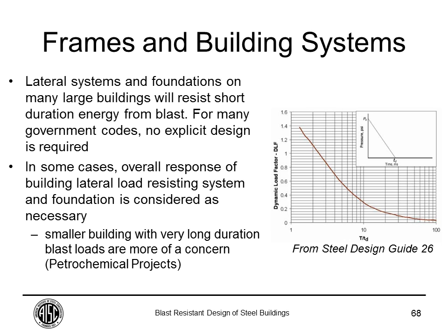So let's just talk about frames, which is the very last point in the outline. Generally, frames are not required to be designed for blast resistance because they have an inherent resistance to blast load. The main reason for that is, if you look at this plot on the right, the natural period of frames in terms of their sway motion, which will be the T, tends to be very large. And the duration of the blast loads, as we saw, is in the millisecond range. So the ratio of T over TD tends to be really large.